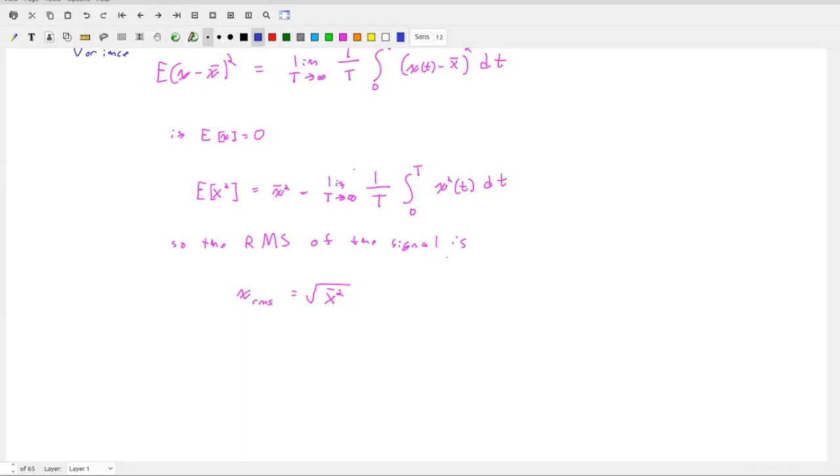So let's consider a non-stationary signal. An important measure of interest is how fast that variable changes, right? Does your mean change 100% in a second, or does it change 1% in a second? Those are very different mean changes. So this is important to understand as it provides context for how long a signal must be sampled, right, before you can get a meaningful representation of the signal to be calculated.